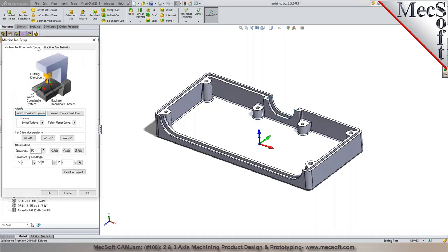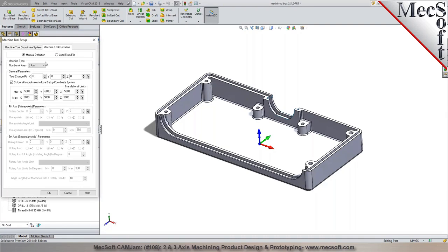So when you go into Machine, you can go to Machine Tool Definition, and this is where you specify the number of axes. So for 2 and 3 axis, you leave it as 3 axis. We have 4 axis capabilities, starting with Expert configurations, which can be like a rotary table where you can index or do a continuous rotation of the part. Index 5 axis, also known as positional or 3+2 machining, is included starting with our Pro. Premium includes simultaneous as well. So as you're looking at the Pro configuration, you can do 3+2 machining, also known as index 5 axis machining. So you can go 2, 3, 4, and 3+2 machining.